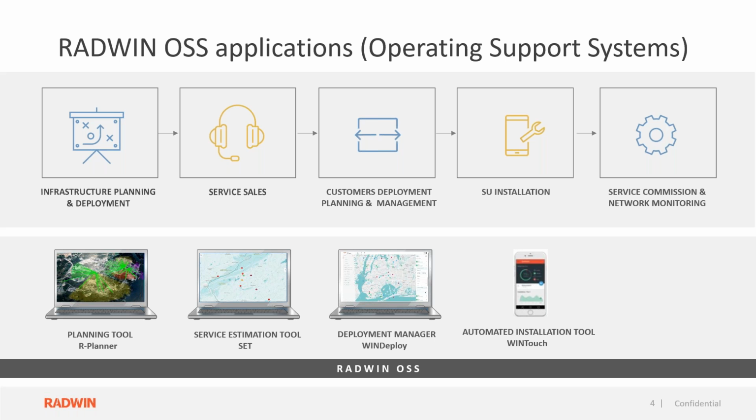Alignment of the antenna becomes much easier and simpler, where the installer can get a very accurate alignment of the antenna, and the decision is made by the application. The installer just needs to follow the instructions, and definitely he will get very good performance if he just follows the instructions on how to align the antenna.